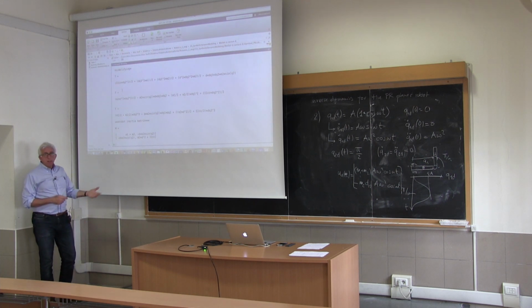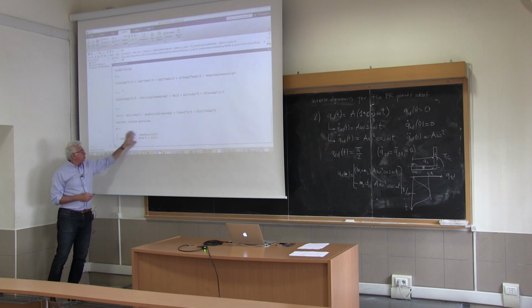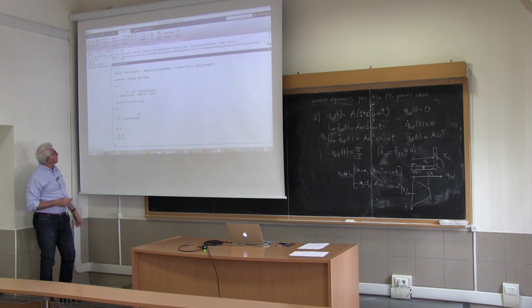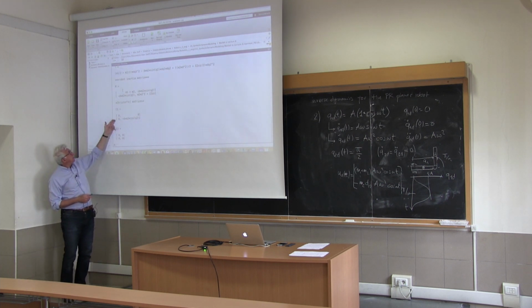Now from this, we compute the Christoffel symbols, so we do the computation using the columns of M and the total matrix, and we do partial derivatives properly organized with respect to the q variables. And so we have the Christoffel matrices. This is the first matrix, which should be introduced in the quadratic form in the velocity.